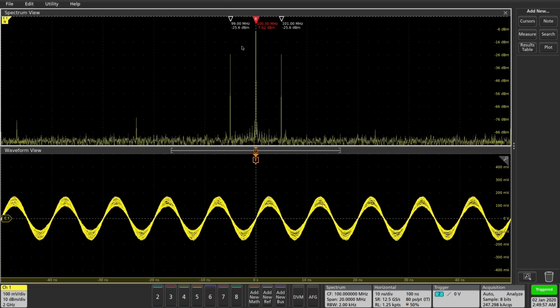Now in the frequency domain, you can see a tone on the left and the right, very symmetric on the upper and lower sideband, and you don't see the Bessel function tones because this is an AM modulation. But remember, for small modulation, AM and PM would be indistinguishable. That's why carrier removal is so key. The only difference between them is actually in the phase domain. You cannot see it in the amplitude domain like we see in the spectrum there.